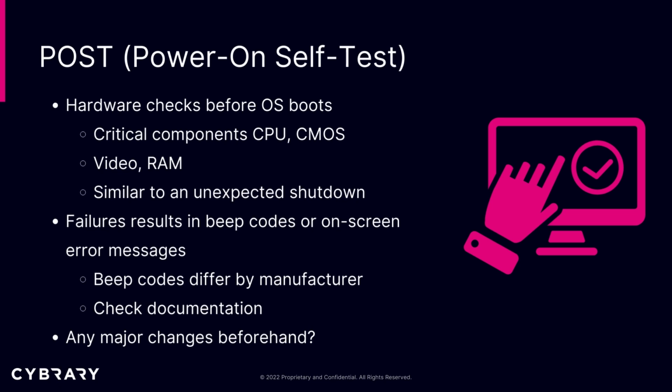Now, these beep codes differ by manufacturer, so it's good to have the manufacturer's information about that motherboard to determine what the beep code is telling you. So you check your documentation. One of the things you want to go back and check is whether there were any major changes beforehand, any newly added devices or anything along those lines that would trigger that beep code.